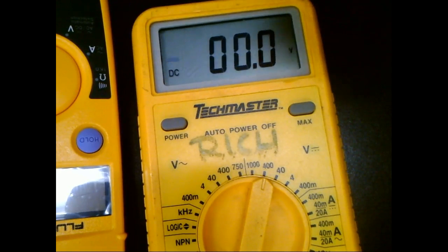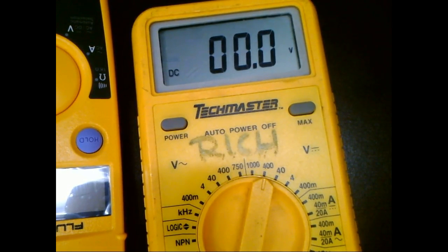So when you have your meter on DC, it gives you the average of what it sees there. So they had to come up with another method to get the work we get out of here. The problem is I get as much work out of my negative alternation as I do my positive, right?